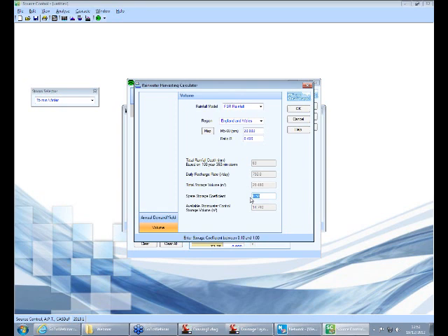So in this case, coming out of the recommendations from the standards, we apply a 0.5, so basically 50% of the storage is available for rainwater. The rest we assume is still full from the previous storm events. So what we actually end up with is just under 15 meters cubed of storage available in the tank.